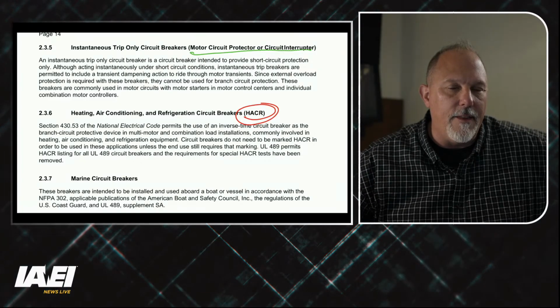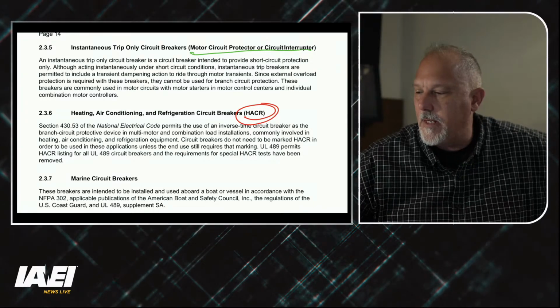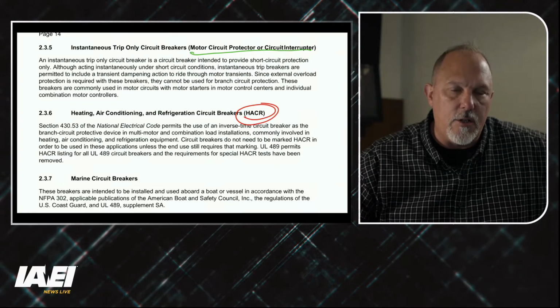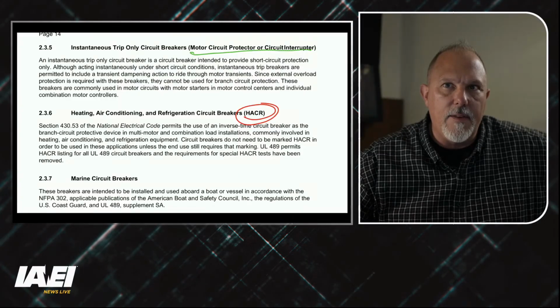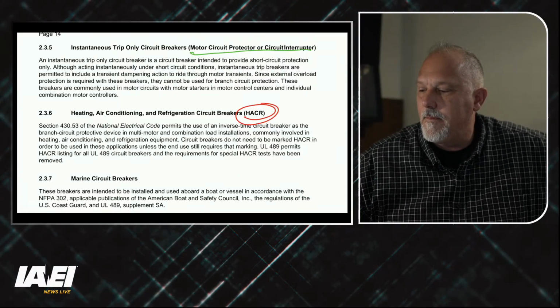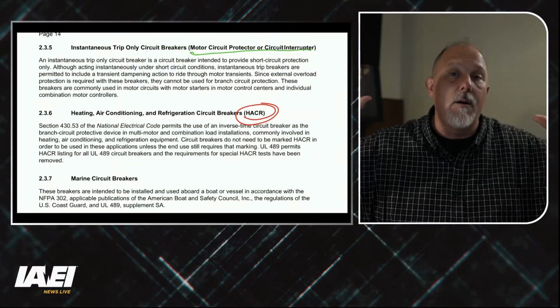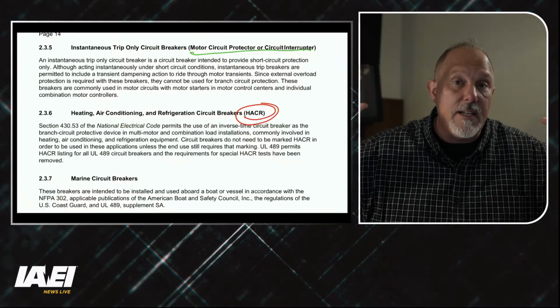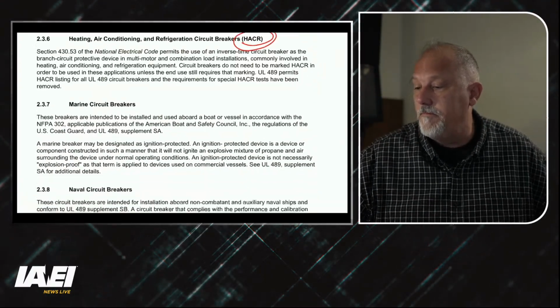I'm feeling confident that all of these things are HACR rated. Not everything is switch duty, but I believe everything is HACR rated. But I may be wrong. Look for the HACR to see if it's on the breaker.